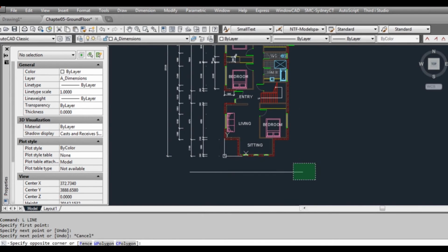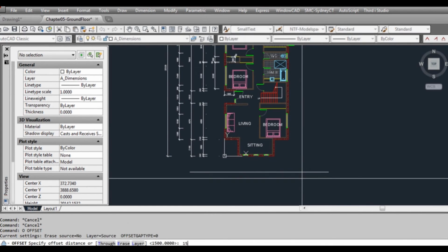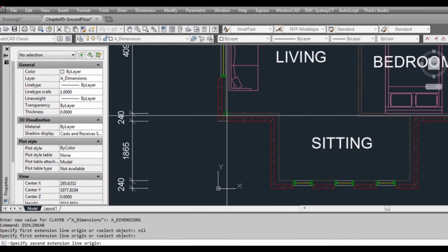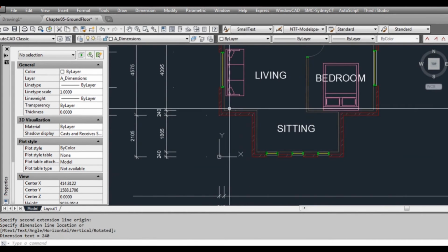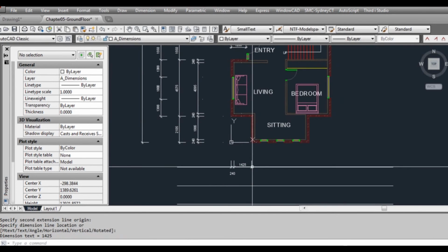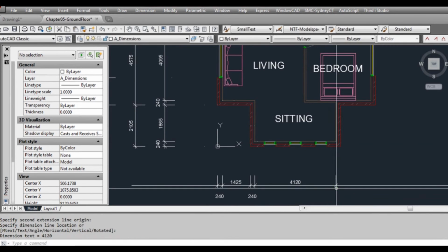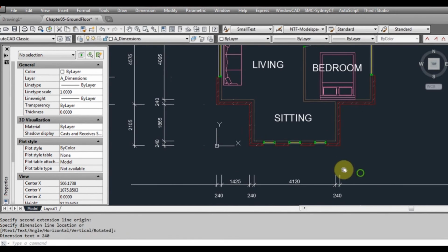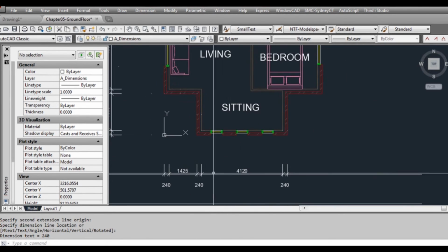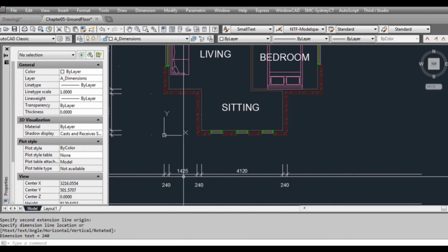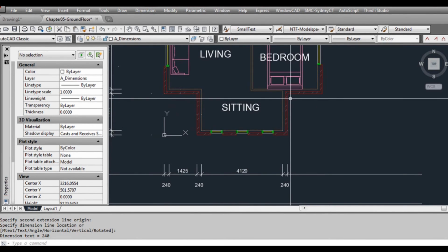I think, yeah, we're going to need all this sort of setup eventually anyway, so I'm going to continue on. We're going to draw some more lines here. I may have missed some dimensions whilst doing this, but as I've said, it's not really about so much being accurate with this right this moment. It's more just giving you an understanding about how to go about doing these dimension lines. As you can see, I've been able to create these dimension lines very quickly because I started one dimension, and then every time I finish doing the dimension, I've just been able to press the space bar or enter key to restart the same command, which is quick and easy to do.